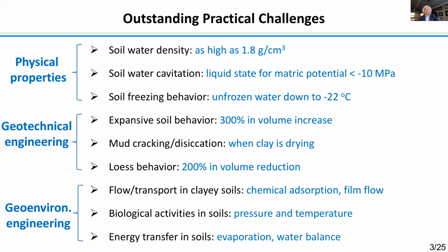Another thing is water in soil, where we traditionally use Darcy's law. However, that applies in the large pores. When the water goes close to the particle surface, there is another phenomenon that is well documented to some degree and starting to be quantified. It's called film flow. They are basically creeping around the particle surface. Why is it so? Also very much related to the pressure.